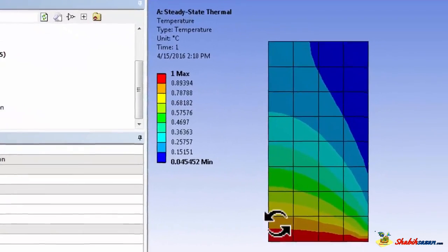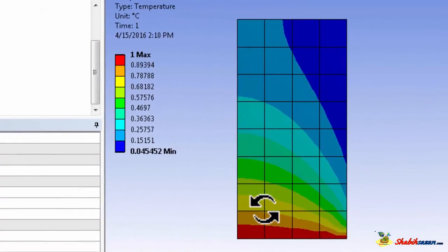What it did was, to get the temperature value at any arbitrary location, it's just doing an interpolation from the 8 surrounding nodal values, and that's quick, as opposed to having to invert a stiffness matrix, which tends to be the most time-consuming part.